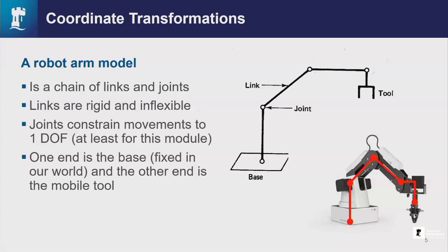What you don't want is to move a pallet and then be off at an angle. So the mechanism within this always means that this part remains parallel to the ground. You never have to adjust the orientation of the end effector with this robot. And this is the robot you'll use for the coursework. You'll be given a couple of tasks to do, a bit of analysis, and then you'll program it to complete a task.